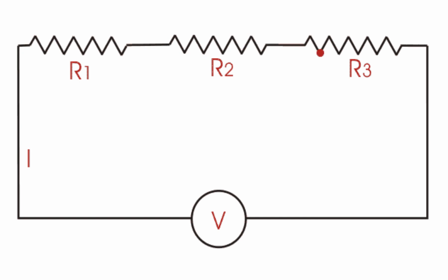The general voltage divider formula. Another method to determine the voltage drop across series elements is to use the general voltage divider formula. Since the current flow through a series circuit is the same at all points in the circuit, the voltage drop across any particular resistance is equal to the total circuit current times the value of that resistor.